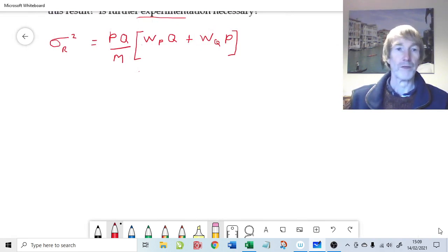If we use C as component P, then we know that WP will be pi over 6, because it's a sphere, that's the volume shape factor, times the density, I'll just leave that as rho rather than rho s, times the particle size, which we know is going to be 50 microns, but for the moment let's just call this xp to make it a little bit more general, and we need to cube that particle size, and that will give us the mass in grams if we're working in CGS units for WP.